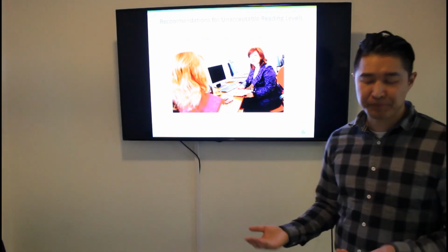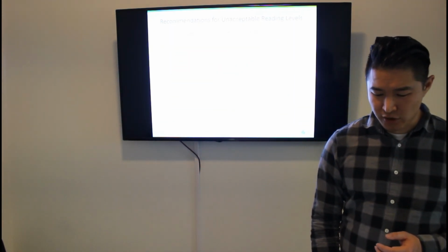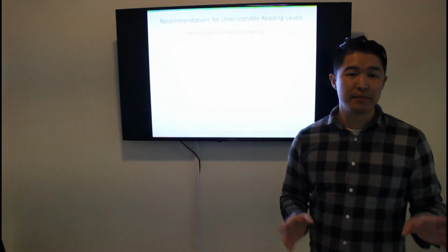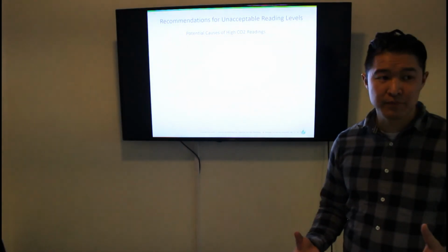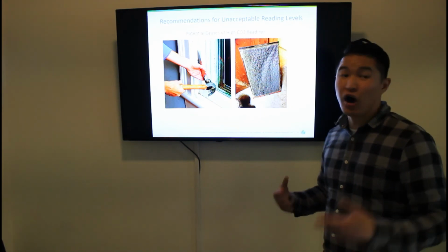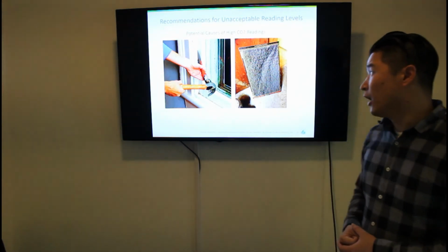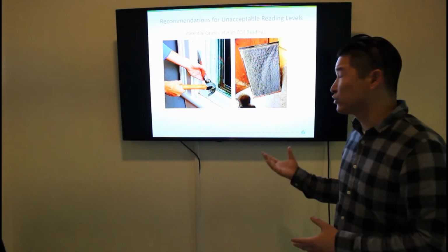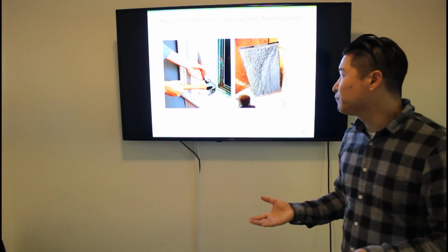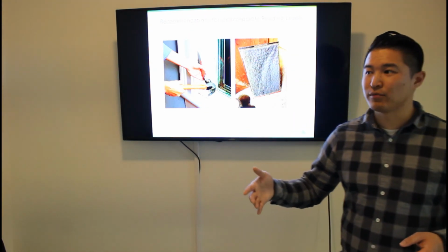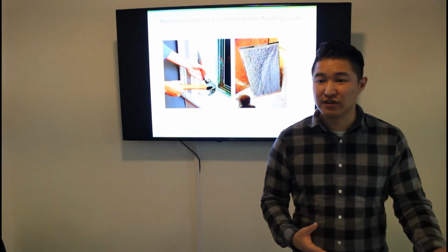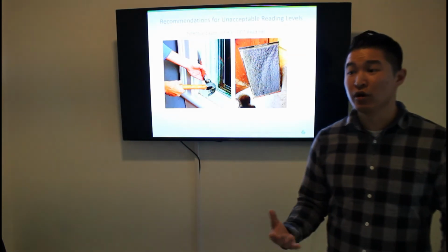Now, the other thing that I wanted to point out is that for carbon dioxide, you would take that same approach. But before you actually do start to conduct a survey, you definitely do want to work with a building engineer to see if there's any issues that are causing those high CO2 levels, okay? A lot of the times when I do site visits, I've noticed that filters are super clogged, to the point that they're almost solid. There's windows that are not operating. Sometimes the outside air fan is shut off or the damper is completely closed. So things like that you probably do want to note or investigate at least with the property management team in order to resolve those issues.